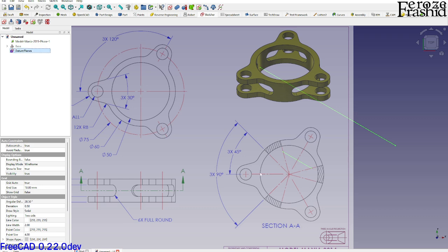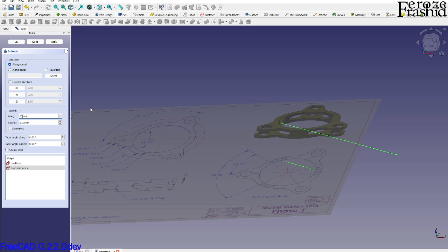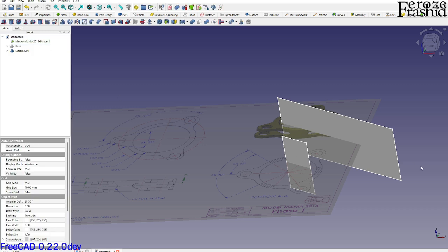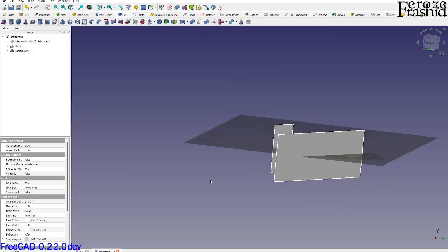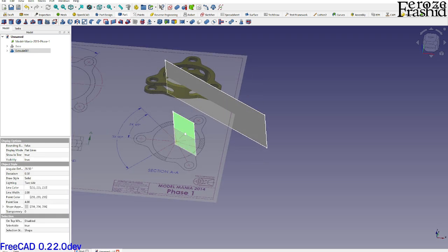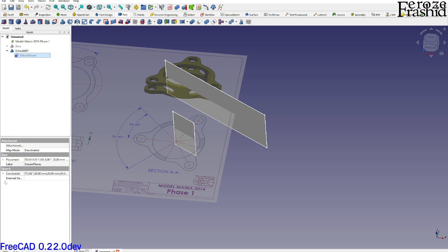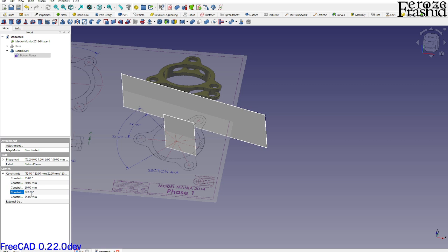So these are my two datum lines that I can go ahead and extrude for, say, 50, doesn't matter, maybe both ways. And there, so I have two datum planes. Now this plane is actually pulling data from our sketch, and I can go in there and find that 90 degree. I can make that 120 easily. So that's kind of where the idea is.